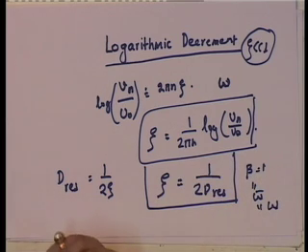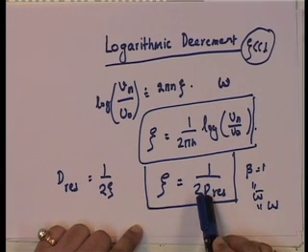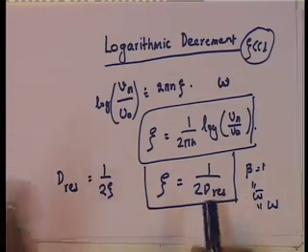The problem here is that in real life, when you have very small xi, the D becomes very, very large, and when you have very large dynamic amplification and you are exciting a system and it starts rotating, as you come close to this, it starts doing this, and you get a feedback into the system. You start what is known as a feedback loop, and you cannot really maintain resonance in real life.